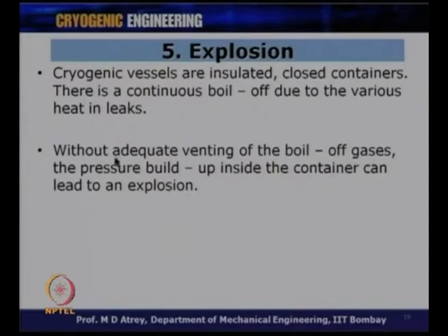So, if adequate venting has not been taken care of, and because of heat inleaks or sudden heat inleaks, the boil off and pressure build up can happen inside the cryostat, inside the container, and suppose your safety devices do not function properly, or are not taken into consideration, it can lead to an explosion, and this explosion can be very, very bad. It can be fatal again. So, these aspects are very important, and therefore, all the safety devices have to be first understood and they should be part of your design.